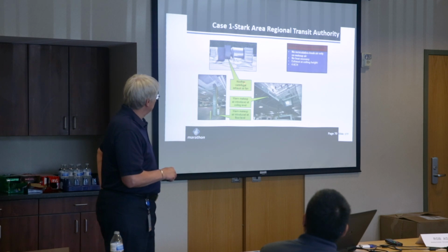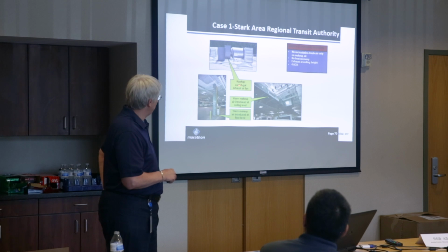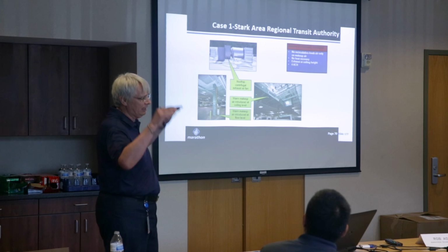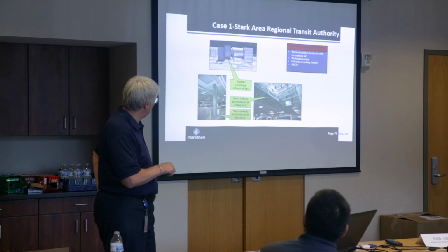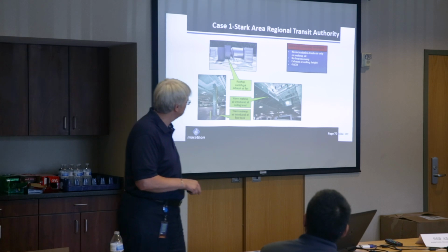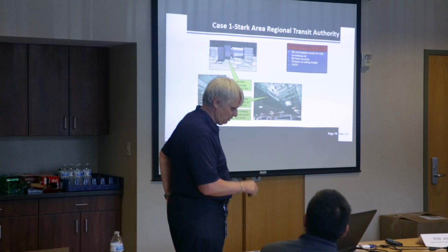They have these rooftop centrifugal exhaust fans. Here's their ducted system, where they're blowing warm makeup air in at ceiling level, but you can see they are pointing it down towards us. They also have warm air coming in at the floor here, so a combination of the two. 4 air changes per hour.